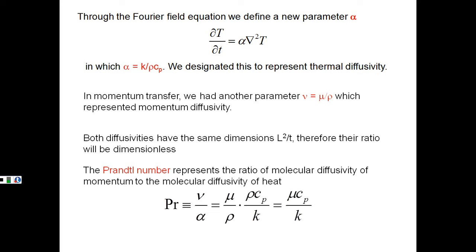So do you guys remember what we did with that Schmidt number? What was it useful for doing? That Sc value, when were we calculating that? No ideas? Yeah, it was for the Sherwood number. So remember, if our Sc value was equal to 1, then we had a reduced form of our Sherwood number, which was just a function really of the Reynolds number and this messy coefficient in front. And then when the Sc was not equal to 1, we raised the Sc to the 1/3 power. We included it in that calculation of the Sherwood number.